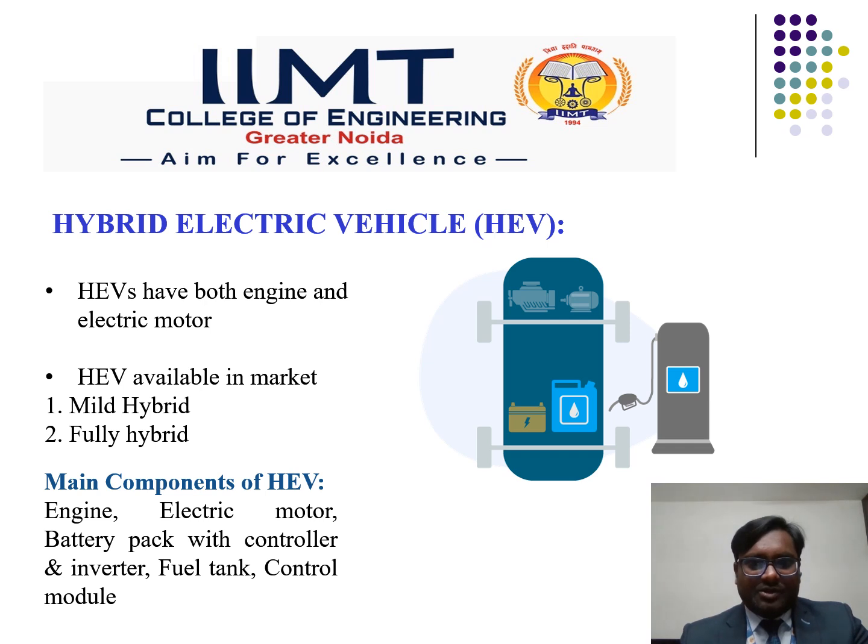An HEV cannot plug in to outboard sources of electricity to charge the battery. Instead of this, the vehicle uses regenerative braking and the internal combustion engine to charge. The vehicle captures energy normally lost during braking by using the electric motor as a generator and storing the captured energy in the battery in the form of direct current.